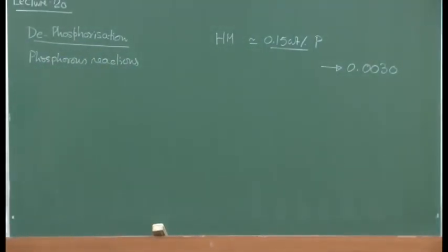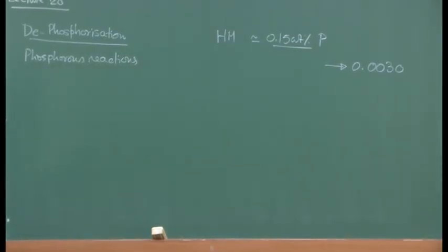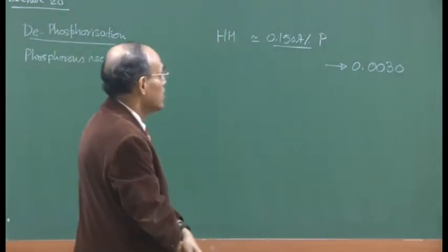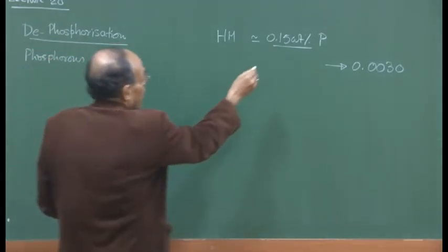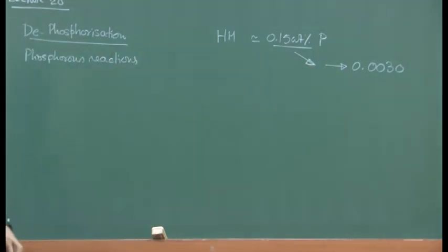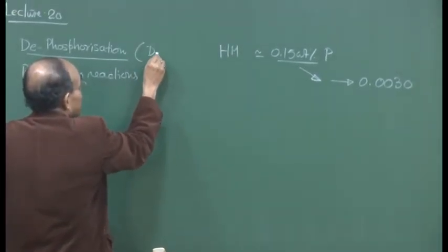It is not suitable for all applications, but a good steel produced by primary and secondary steel making for some critical applications should contain a maximum of 30 ppm phosphorus. So, quite a bit of phosphorus is required to be eliminated during oxidizing refining, and this removal of phosphorus is termed dephosphorization.